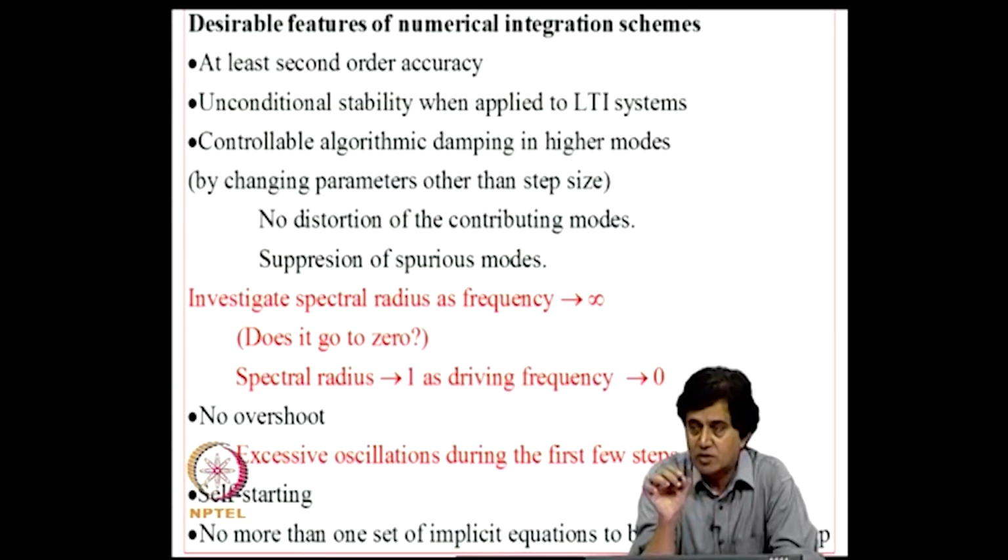Then suppose that the highest frequency is, say, 20 hertz, as perhaps in the case of an earthquake engineering problem. Then we should ensure that the finite element model we make has acceptable accuracy on eigen characteristics, maybe up to say 50 hertz or 80 hertz, 3 to 4 times the highest frequency present in the excitation. Over that frequency range, we should capture all the modes present in the structure with good accuracy.